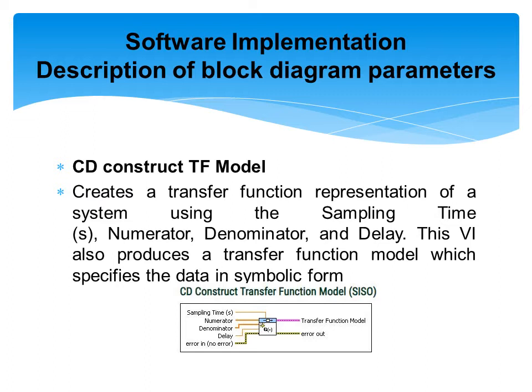Here is a small description of this icon of the LabVIEW software. It creates a transfer function representation of the system using the sampling time, denominator and delay. This VI also provides a transfer function model which specifies the data. Here you see the inputs are the denominator, delay, error in, sampling time, and the outputs are the transfer function model and the error out. You use the input and output points according to your requirement.